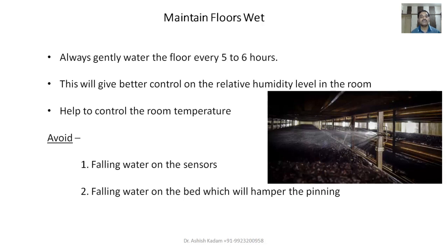If your flooring is dry, it will absorb the moisture from the room air, and ultimately the room air will absorb the moisture from your compost. So ultimately it will impact the moisture level in the compost. That is the reason we have to keep on gently wetting the flooring. It does not mean there should be formation of ponds. There should be proper slopes, no accumulation of water, and a proper drainage system, so there are no homes for the growth of bacteria and viral infections.